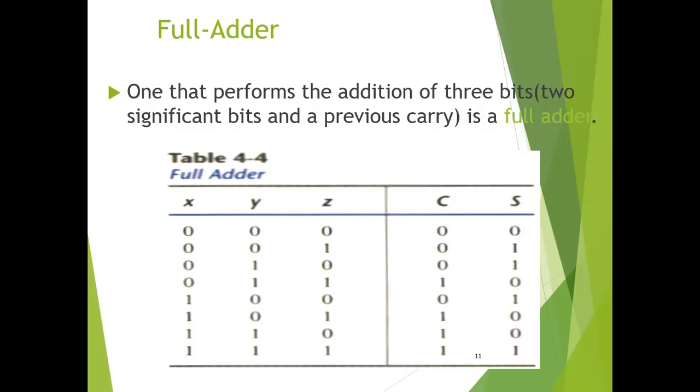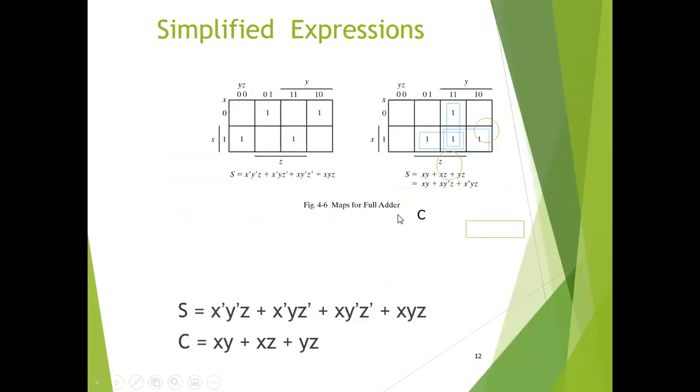And for the output of the full adder circuit, we can see that from this truth table we can construct the output functions for these two output bits, sum and carry. From the truth table we can see that for the sum bit there are four ones, and these are placed in the K-map here, for the four input combinations of minterms.